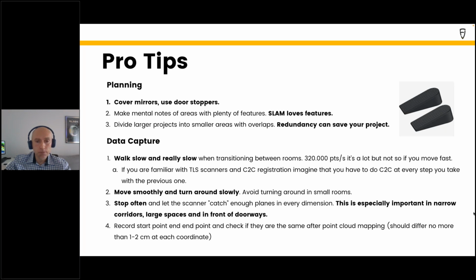So avoid sudden movement and think of continuity of your trajectory. If possible, cover mirrors in some way beforehand, before you start the scanning, and keep in mind what the scanner saw at your previous step, and then you plan your next step.